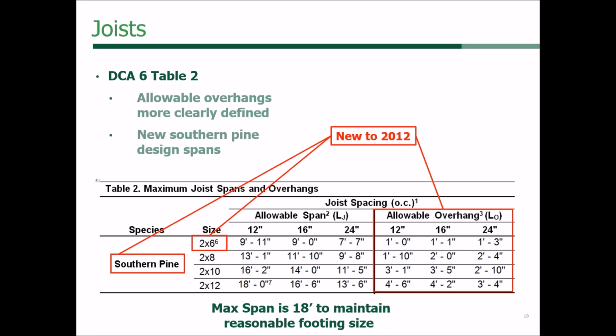The second thing is that 2x6, and again, that's for like landings or very small decks that you don't really need a 2x8. And there you'll see that there's a footnote 6, and we'll talk about that footnote 6 a little bit more, but it's basically for guard attachments that you shouldn't be using 2x6s, but rather 2x8s.